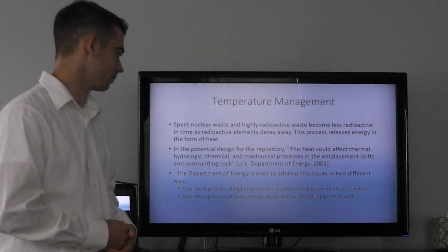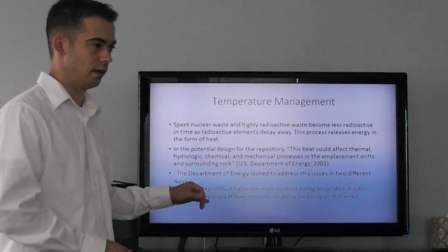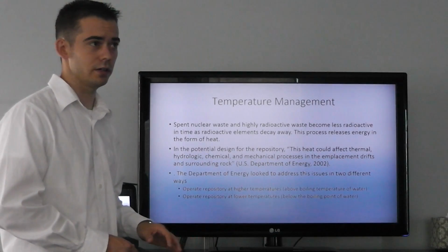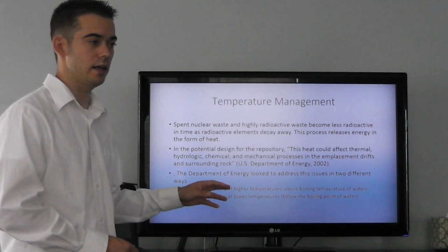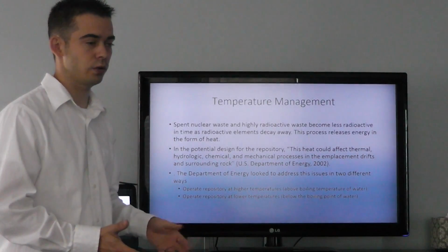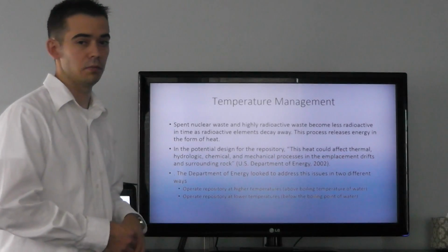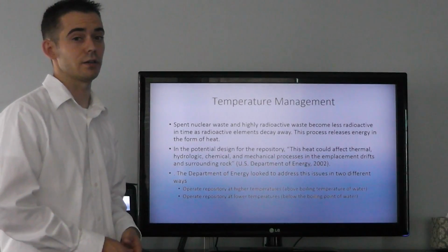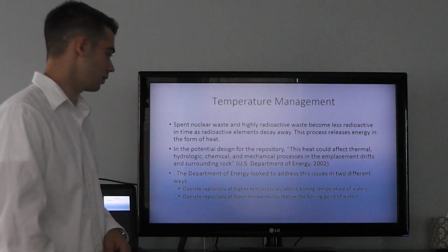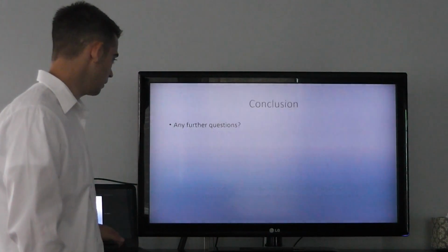And also they like the lower temperatures because as long as they are able to maintain the site at less than 85 degrees Celsius and the humidity under 50%, the Alloy 22 material that the package is made of, and the engineered barriers, are less likely to corrode. So that's some of the benefits of operating at a lower temperature.